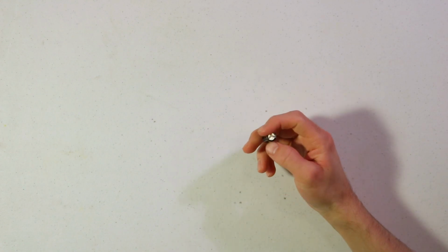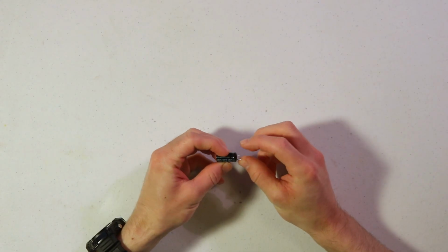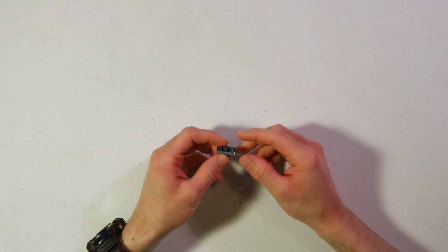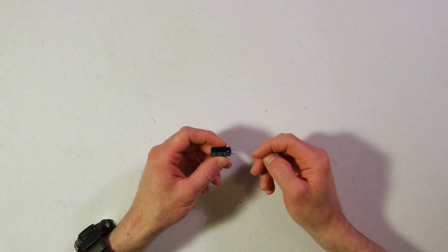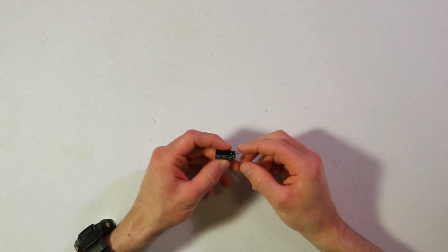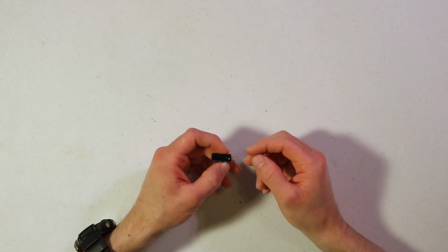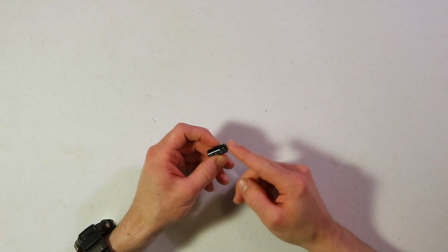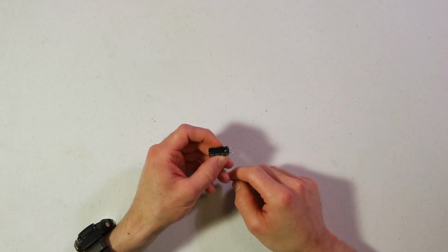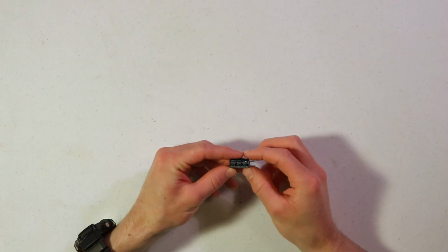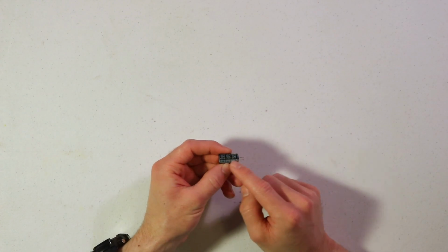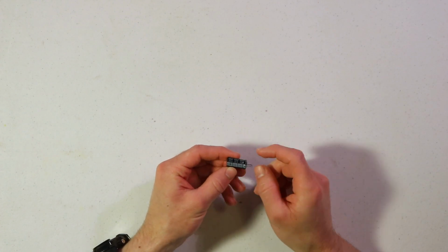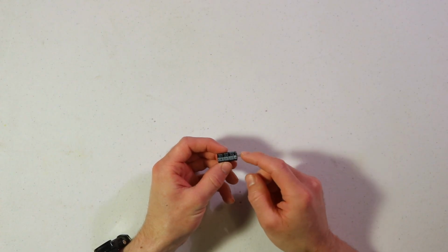The next component is the capacitor, and the basic function of these is just to store charge, which if you measured it across the two leads, you would find a difference in voltage. The capacitors that you have are polarized capacitors, meaning there's a positive lead and a negative lead. The way you can tell which one is which is the positive lead is going to be longer than the negative lead. The capacitor I have here has already been trimmed short, so I can't show you the difference in lengths of the lead. But the other way you can tell is look at the side of it and you'll see the strip where it's got maybe negatives written on it or maybe zeros or something like that. And that one is going to be the negative lead.